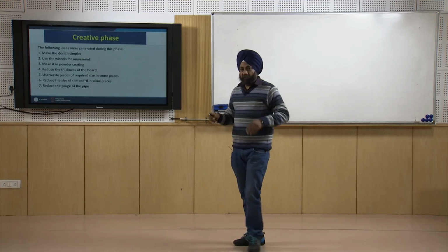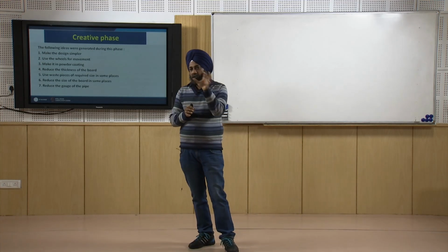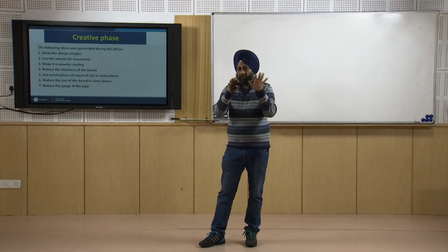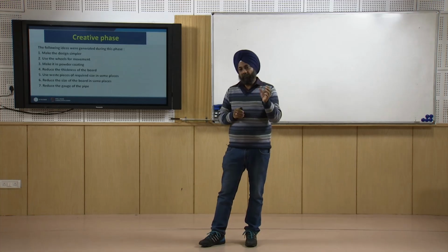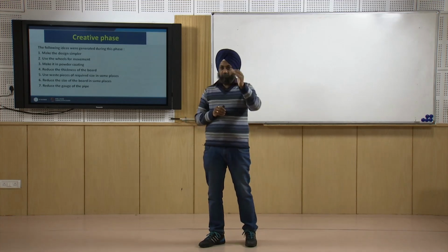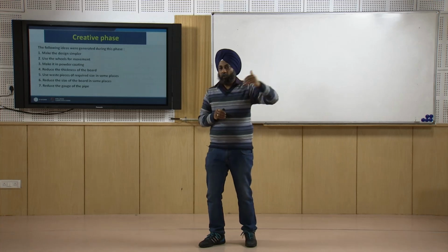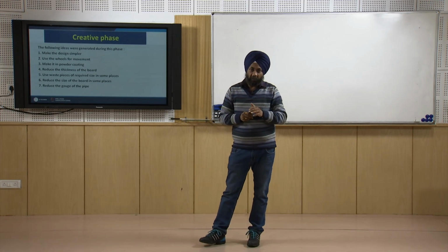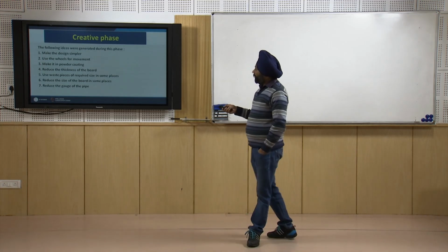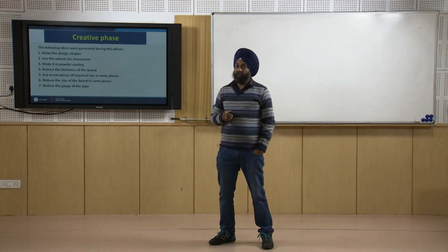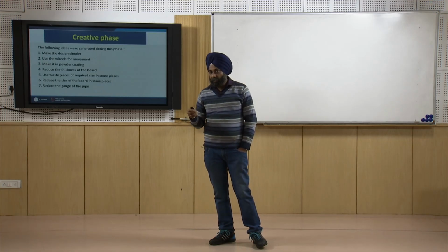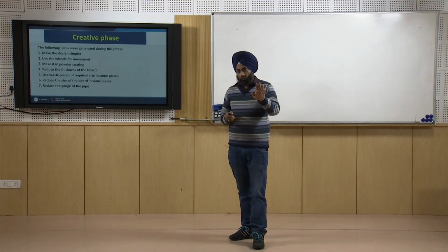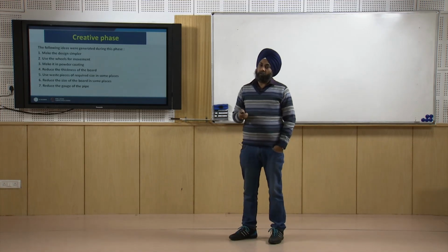Now the creative phase. This is just the information that steel frame is contributing this much, and the leg frames are contributing this much, and then we have given the weights to the individual components, and we can also calculate the percentage contribution. If we do not want to go into the weights technique, we can directly see the percentage contribution of individual parts in the overall cost of the product. Now we have to see how we can make this Divan in a cheaper manner, or what options are available with us to reduce the cost of the Divan without compromising the cost and quality and performance.